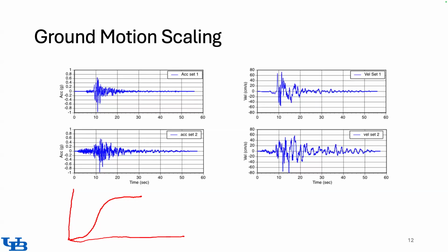So your structural response is going to be influenced mostly by this part of the ground motion, not so much by the P waves, because they are much smaller in amplitude. So basically S waves carry more energy than the P waves. Yes. So ultimately, they lead to more response. Correct.